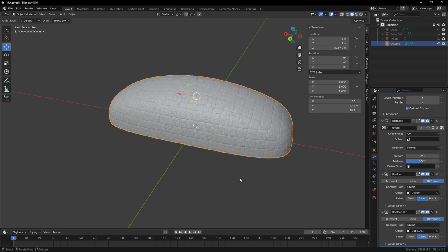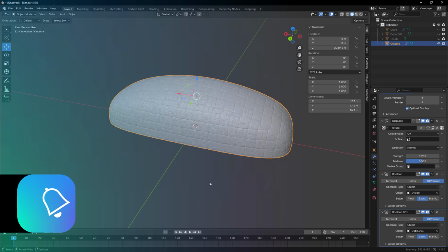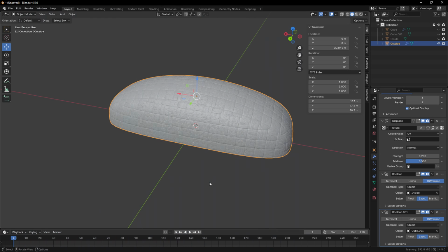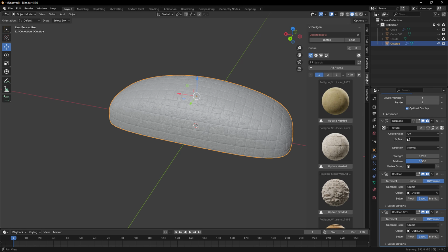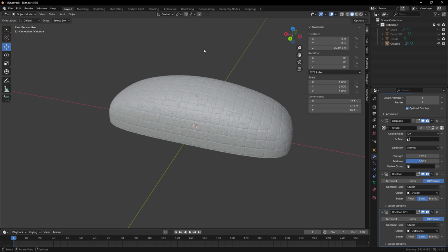Again, if you are going to be doing this, I would suggest you do a little bit of research and search around for the Formlabs option that's available, as well as other 3D print slicers that you can use that do have these options. What I have found is that most 3D print slicers just have a fuzzy skin option and don't actually have a true texture option where you can use an image. So if you have to go the route of doing this manually, that's the way that you can do it with an image. And again, I would also suggest doing a little bit of digging into add-ons like the Polygon add-on. There are also plenty of different websites and add-ons for Blender that have free bump map images or free grayscale images that you can use.